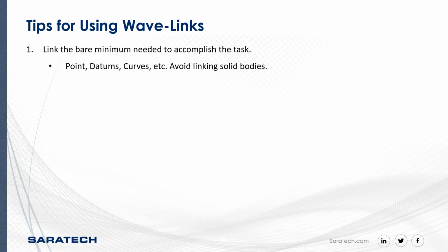So let's go over some tips here. You always want to link the bare minimum needed to accomplish the task: points, datums, curves, etc. You want to avoid linking solid bodies. Those can bloat the load times and the file sizes of your components.